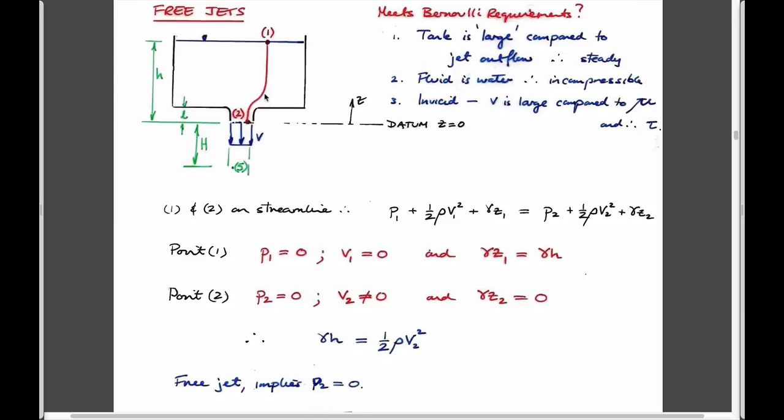And as a function of that, we'd have to say something about being able to constrain the velocities at this point. So if the bucket is small and water's flowing out of it, and as the cross-sectional area of the top of the bucket gets closer to the cross-sectional area of the bottom, then no longer will the bucket level remain constant as a function of time. It will drop down. So it violates our principle of Bernoulli, which is a steady state condition. If we think of it as a very big bucket, a big reservoir, that's code in these questions for saying that the water level doesn't draw down with time, and that the velocity at this point is pretty close to 0. So if this is big, then the velocity here we can set as equal to 0, which makes life easier.